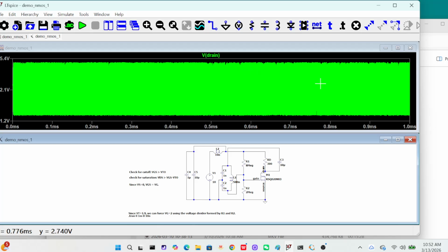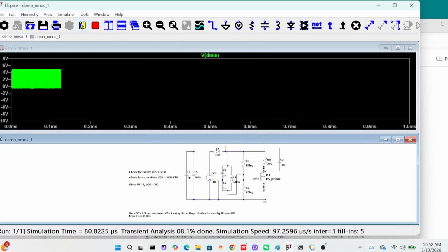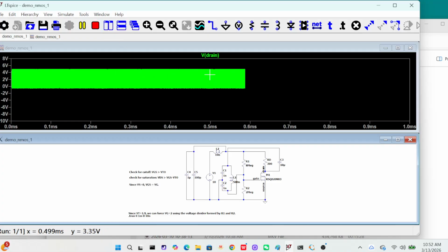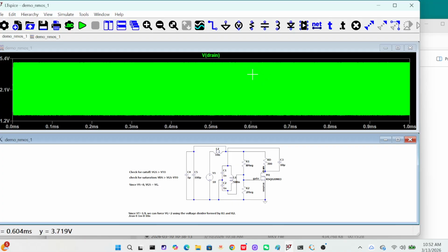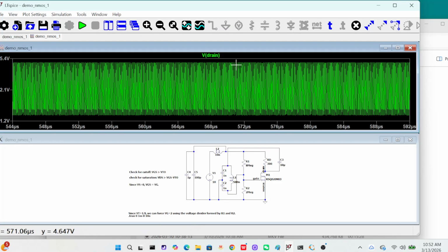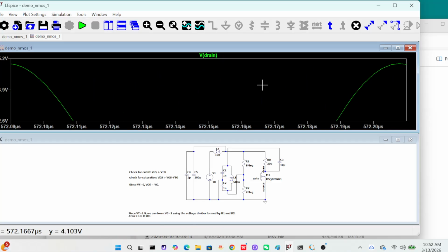Less noise, less noise. So if you increase the capacitance here, now it's clearer. You don't see any noise, so it's much clearer. So this is one way you can stabilize the oscillation, but the frequency will not change. Still 8.8 megahertz, so it didn't change.